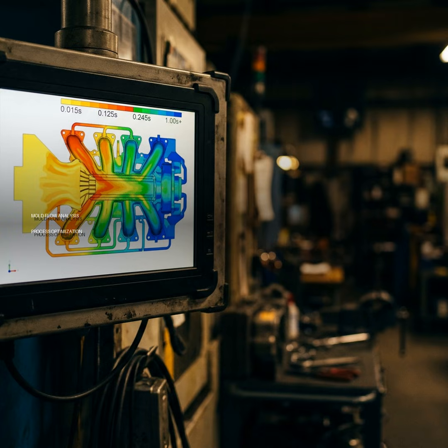Okay, so you can test it broadly and then dial it in for a specific press. What are the key settings you're tweaking there? For filling, you're setting the fill time. The software often recommends one based on part volume and material. For large or complex parts, you'd use multistage flow rate settings to get a uniform flow front. And then there's V/P switching. That's critical. You're filling fast with speed control, but then just before it's 100% full, say 95% to 99% volume, you switch to pressure control. That prevents overfilling and flash. Oh, so you're almost done filling, and then you ease off the gas, so to speak, to prevent defects.